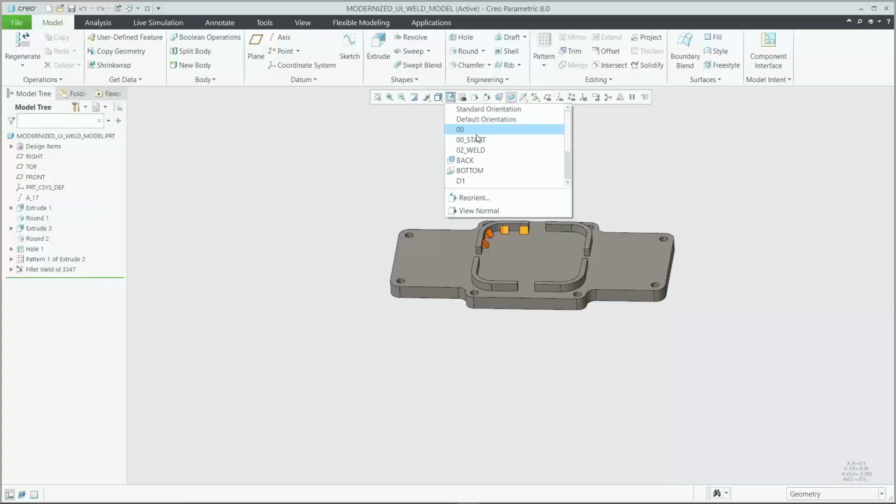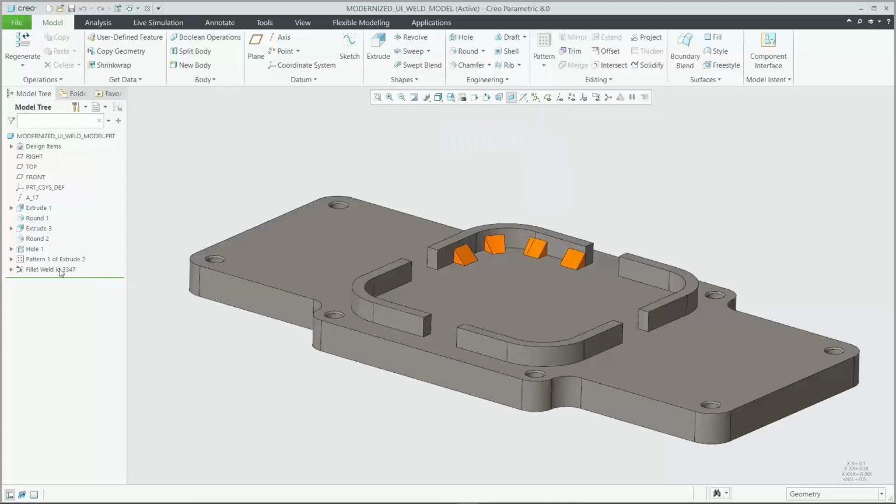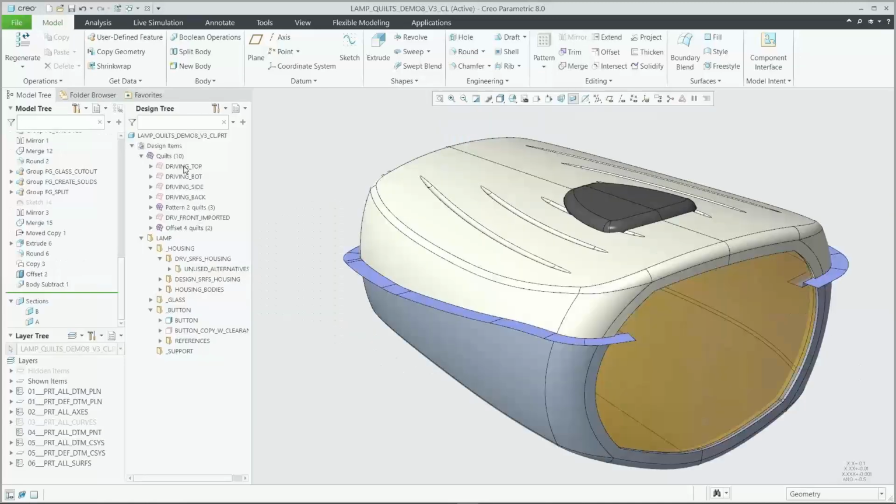And so with those custom groups, we can organize the different items independent of the regeneration sequence of the features. Now here we can reorganize them, drag various design elements based on how we want to organize the model. And users can now work with that. We can set different default custom groups as well. And once they're set, new quilts or bodies that are created will automatically be put into that default custom group. Here we have one for the groups of the part.